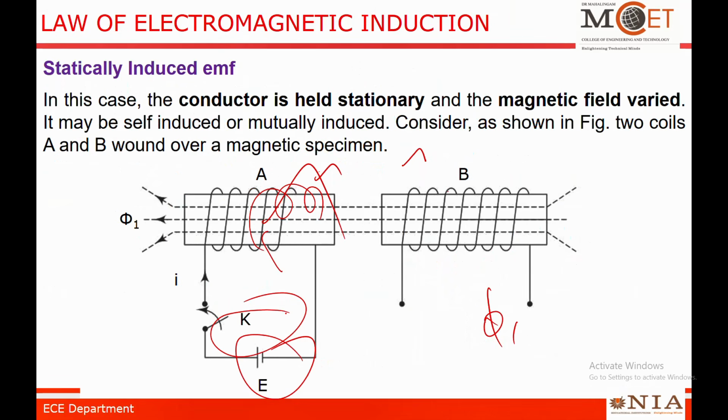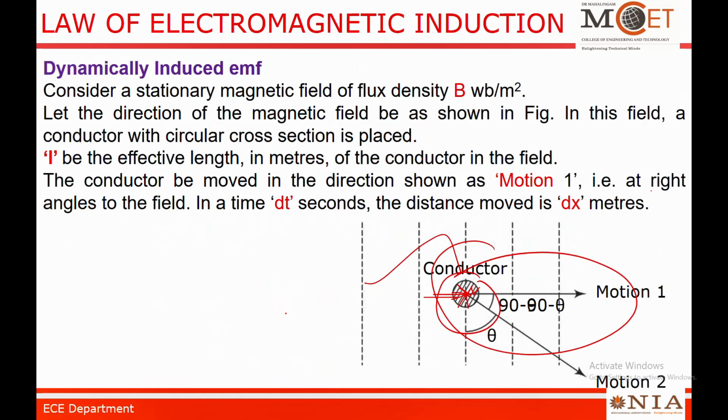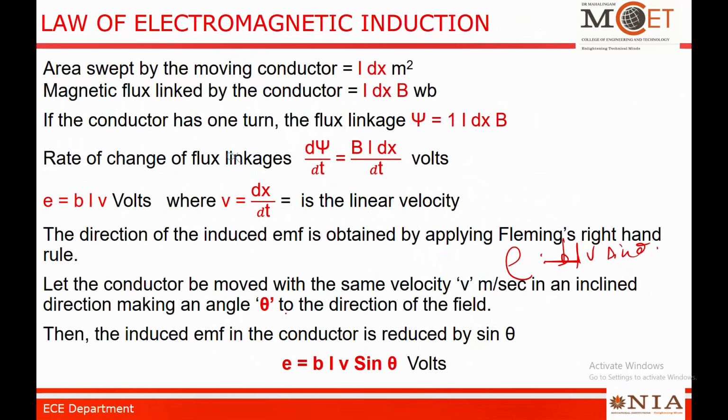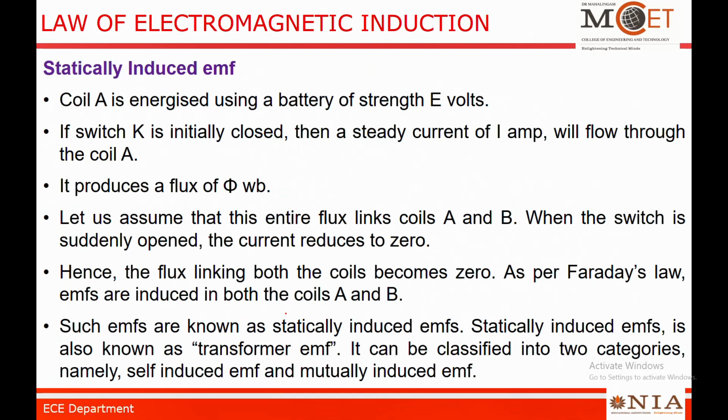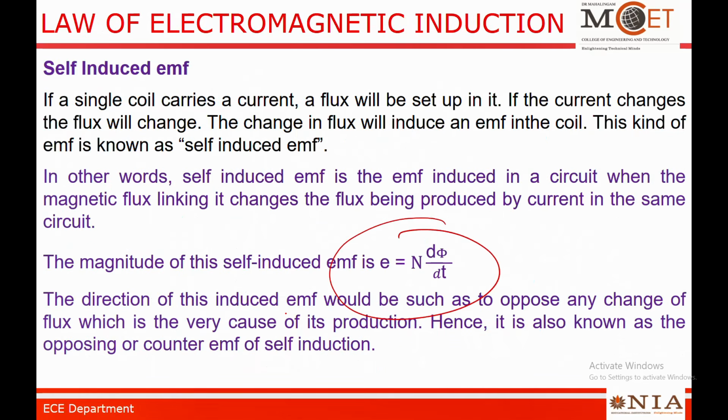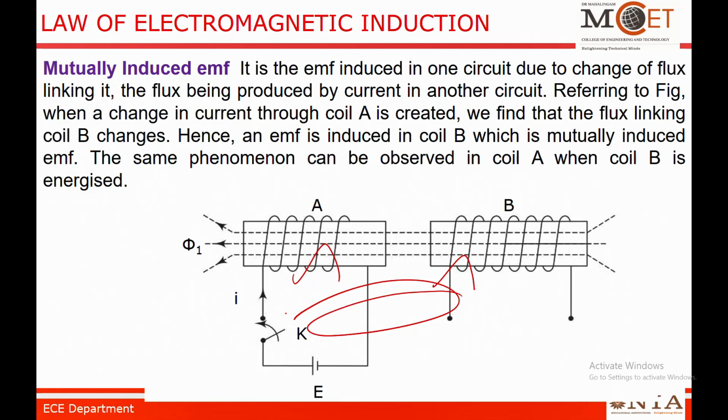So the statically induced EMF, whereas for the dynamic one, with respect to motion, the dynamically induced EMF is obtained from E equals BLV sin theta. Here the equation we consider is E equals N d psi by dt, which means the flux is differentiated with respect to time. This is the main thing we need to consider.